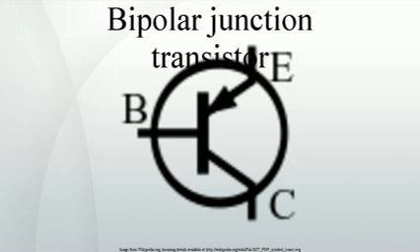Reverse active, or inverse active or inverted. By reversing the biasing conditions of the forward active region, a bipolar transistor goes into reverse active mode. In this mode, the emitter and collector regions switch roles. Because most BJTs are designed to maximize current gain in forward active mode, the βF in inverted mode is several times smaller, 2 to 3 times for the ordinary germanium transistor.